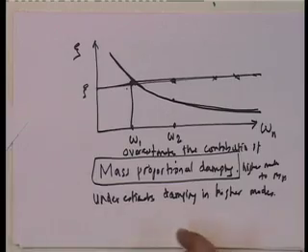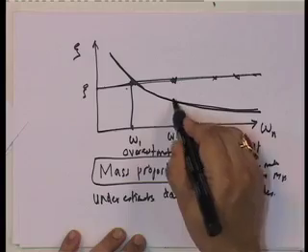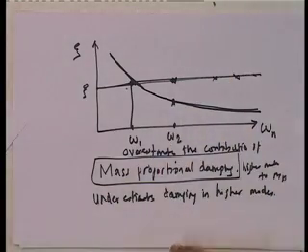I underestimate the damping in the higher modes, because it is supposed to be 5%, but actually I take it as 1%, 2%. What happens? I overestimate the contribution of those modes to the response, right, because I have to take xi n lower and lower. So, actually I am adding more of the higher modes than necessary. That is a problem with mass proportional damping.